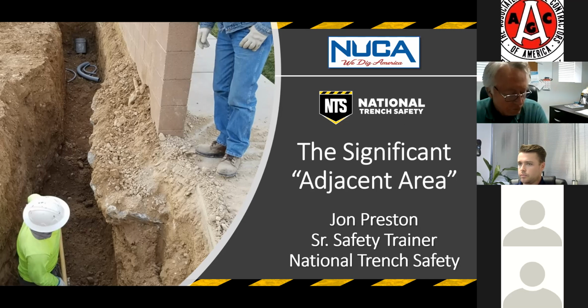So it looks like, John, that Nathan Jonovich asked, what is the minimum height allowed at the bottom of the trench box in the chat? So that sounds like we might have answered that when we talked about the 2 foot. Okay. You're allowed to dig 2 feet below the trench box.